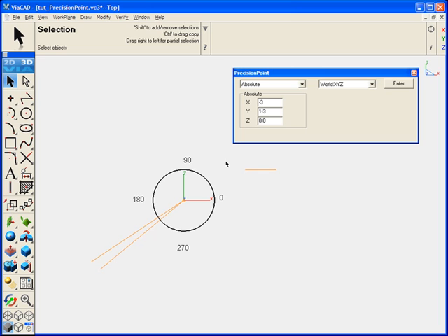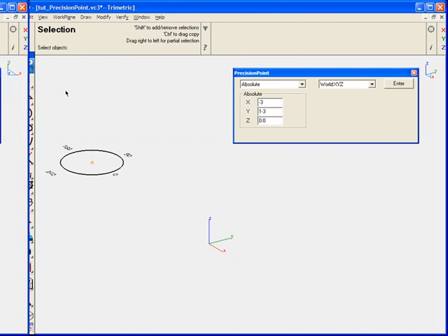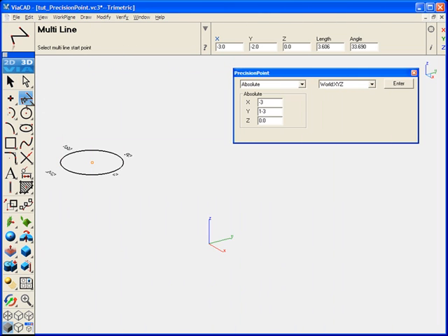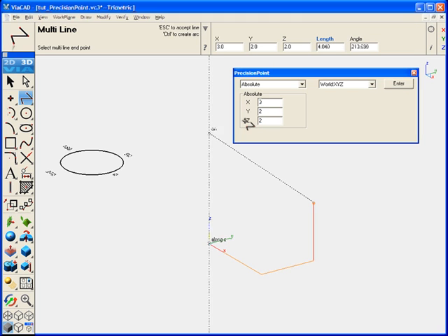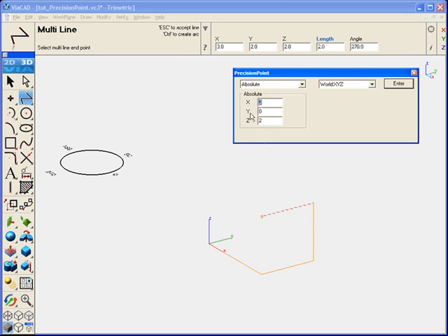Drawing with absolute coordinates is not just a 2D feature. You can also do this in 3D. We've changed our view, used our mouse and cursor to set our starting point at the origin, and now we're using absolute coordinates to draw in the world or XYZ global coordinate system. And again, each point, even though now we're in 3D, is always in relationship with the absolute drawing origin, coordinate 0, 0.